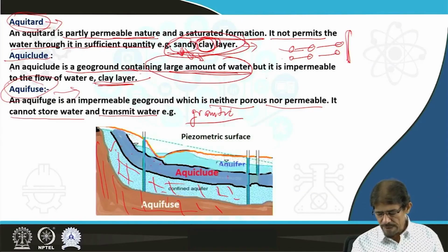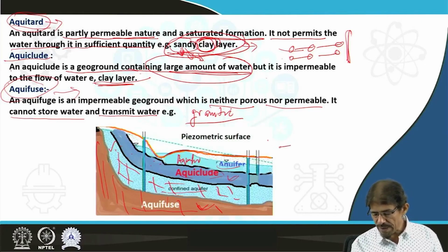So this part also acts as a seal, and this part also acts as a seal. This type of zone is recognized as a confined aquifer. When the aquiclude or aquifuge is not lying above, for example in this case, this is known as an unconfined aquifer. The upper level of water in an unconfined aquifer is recognized as the water table.